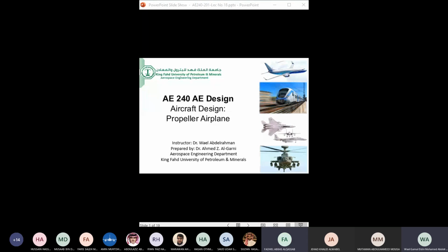Yes, Doctor. We had a problem getting L over D for our airplane because there is not much information on the internet that provides L over D. Yeah, I agree with this. This category of aircraft, you are not going to find someone that will tell you here is the airfoil of the aircraft. But couldn't you find any, not a single one? I found a single one, but I think it was high. It was like 19. What's wrong with that? I think it's too high.